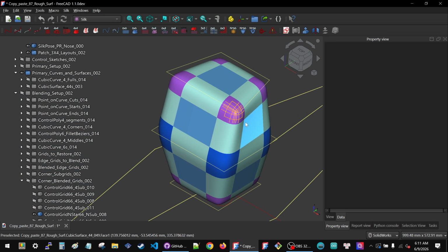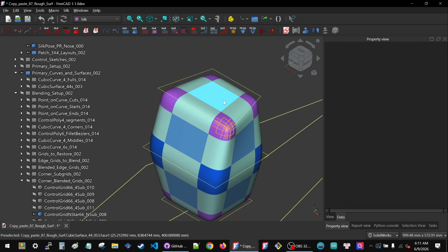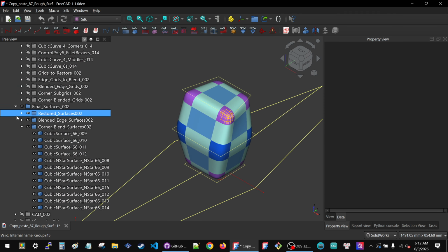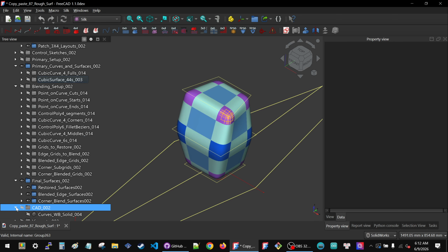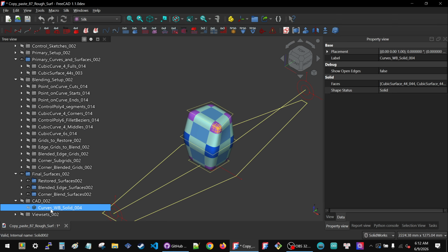What is a mild defect right here, when it's very stretched out, becomes a massive defect. And because we're passing enough surfaces to the Curves workbench solid for this to be a solid, I just saw something happen where, when this becomes distorted enough, the curved solid is no longer a solid, and FreeCAD actually hangs when it's trying to check whether this is a valid solid.